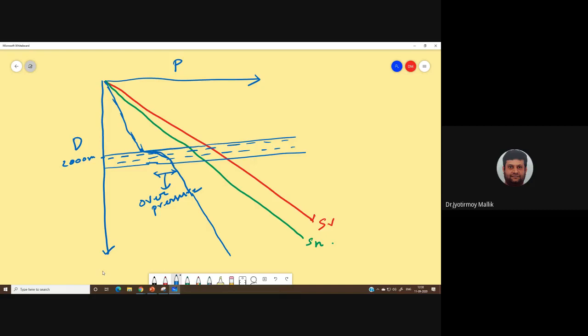This can be a straight line, or this can be of different shapes. Okay, this can also be a straight line, no problem, or it can be a graph like this. It doesn't matter, but there is a step jump in my pore pressure, and that is what we call overpressure.